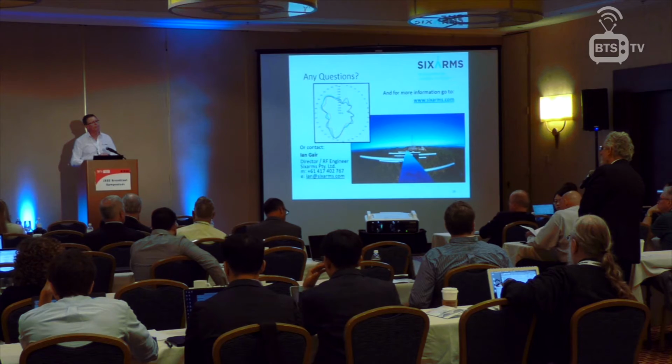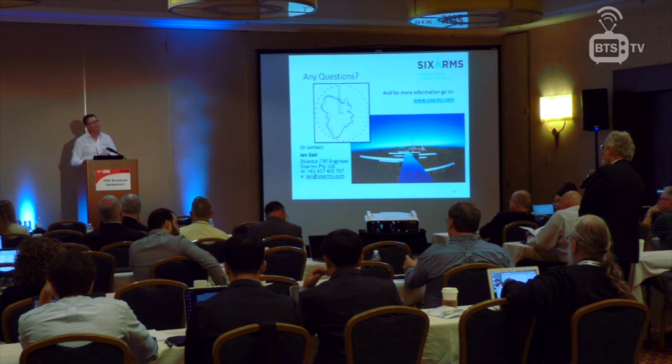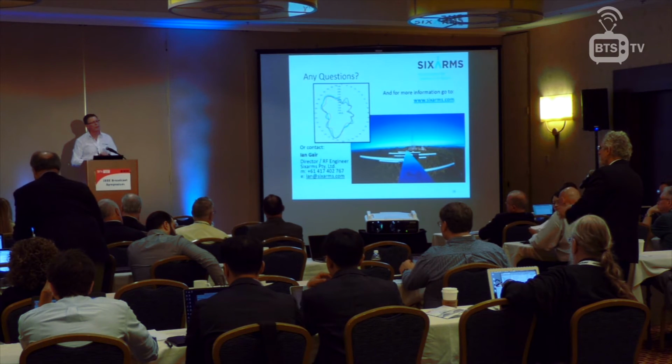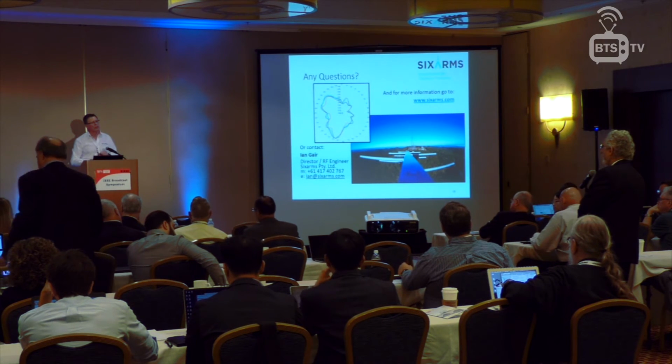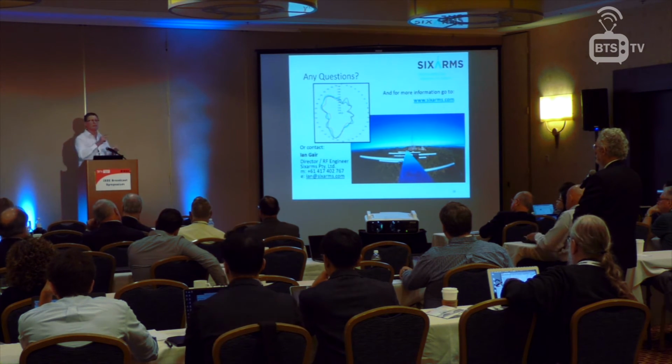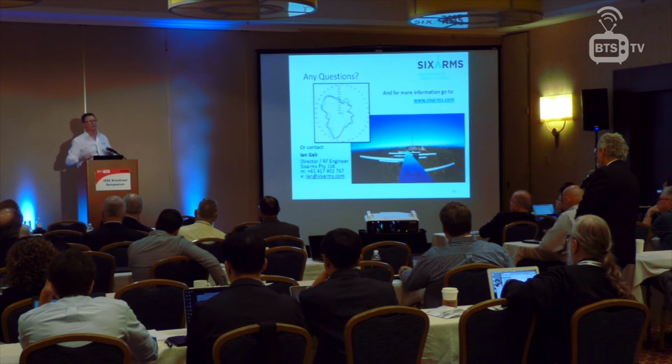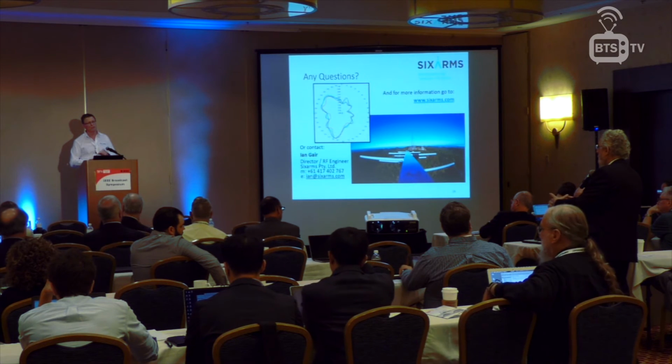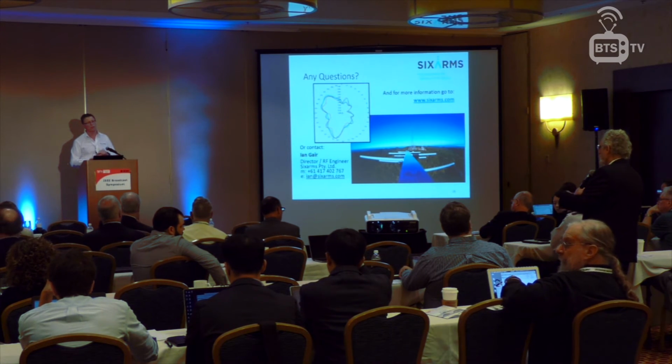And then on the close-in, the near-field measurements, generally you should be able to do the azimuth pattern without concern about near-field versus far-field, because the elements themselves are small in diameter. Yeah, so near field versus far field is not to do with the receive antenna, it's from the broadcast antenna. Right, but the broadcast antenna has identical elements that are arrayed vertically, so the physical size of the antenna, the D, is small for azimuthal patterns as opposed to the vertical pattern.